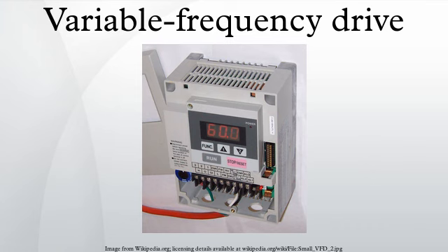Over the last 4 decades, power electronics technology has reduced VFD costs and size and improved performance through advances in semiconductor switching devices, drive topologies, simulation and control techniques, and control hardware and software. VFDs are available in a number of different low and medium voltage AC/AC and DC/AC topologies.